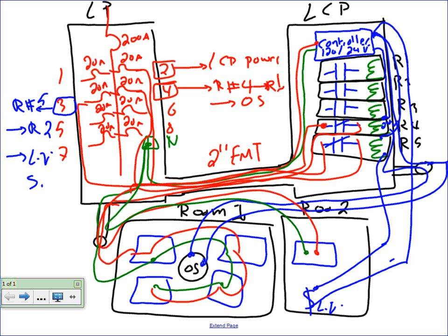Kevin will show you guys there's a lot of much better looking details on sites that do control interface between the two panels. The only thing I want you guys to do is a relay schedule. A relay schedule will show a circuit that's driving a relay, that's controlling a room via some type of control, occupancy sensor or low voltage switch or timer. Okay, before my friend comes, because he is the expert, I'm going to show you guys.